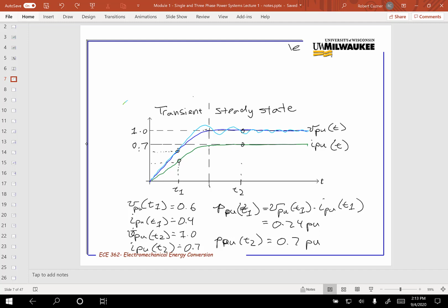So you're probably getting a big surge of current like this, and maybe there's a little bit of loss in that load, but it's mostly an LC load charging up a capacitor. It's like an inrush transient. So the per unit current changed, of course, because the load changed.